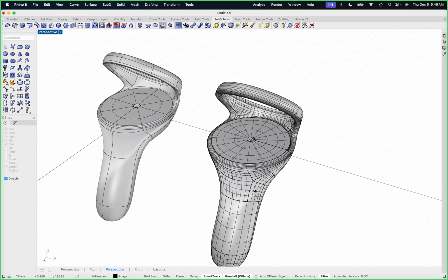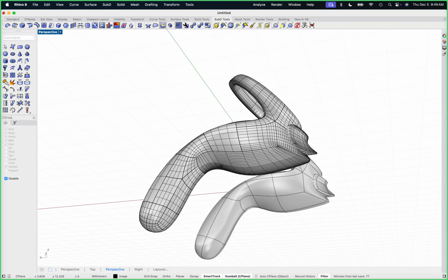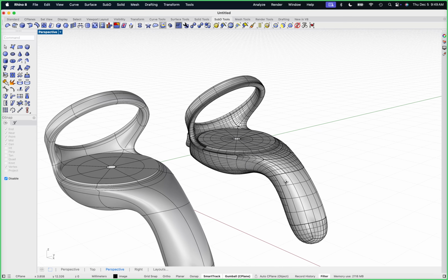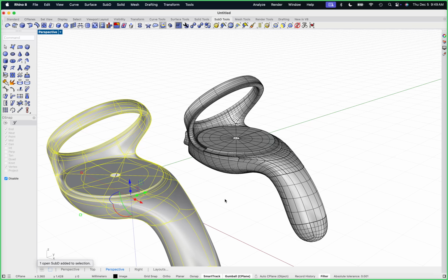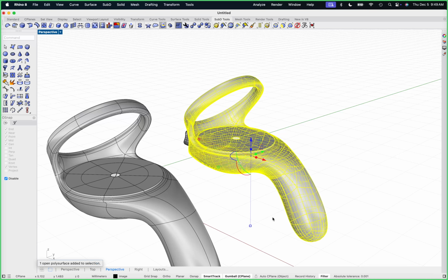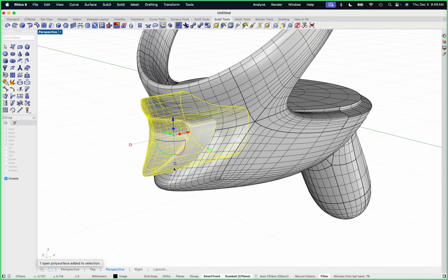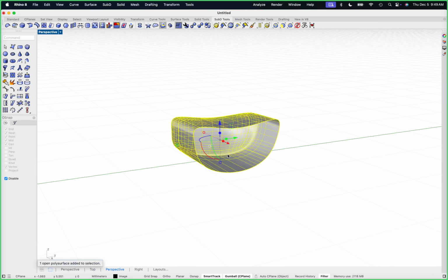Now, we've got a lot of ISO params on here. And you would initially think, well, you just told me to keep everything light. And I did for SubD. That's really important. For the NURBS stuff, because we're doing trimming and booleans and stuff like that now at this point, this is just a regular polysurface. This works just fine. So I can take like this piece and I can cap that.